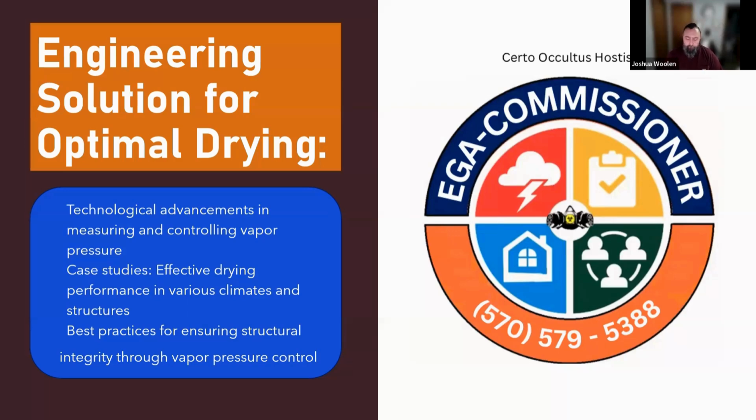When we go to commercial dry out schools and stuff like that, we get a very narrow script about vapor pressure and how it works and everything. Whereas what I'm telling you is that vapor pressure is the key for drying. And it's the key to everything. People like Pat Moffat and Kim Larson and many others will tell you how vapor pressure works and its effect for us in this environment that we live in today.